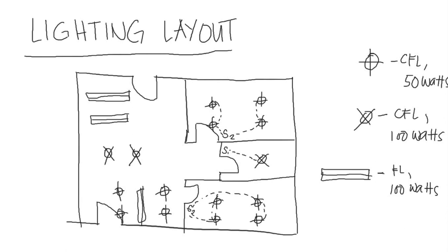So that's it. And then here in the kitchen, I will be using a 3-way, S3-way. The first 3-way will be put in here close to the exit door, and the other switch will be put here. So 2 fluorescent lamps are controlled with the 3-way, and this 3-way is connected here. So this broken line here is the traveler from the first 3-way to the second 3-way.